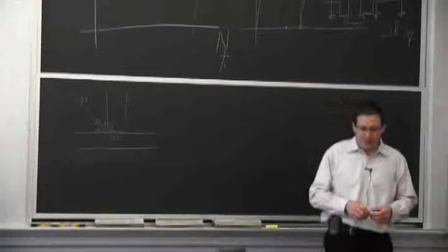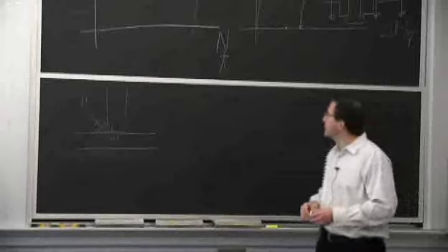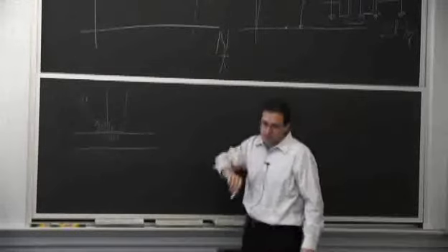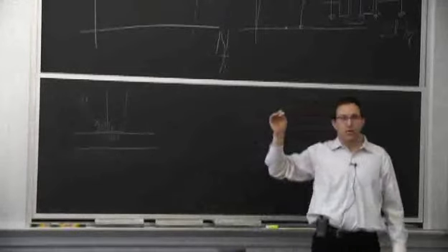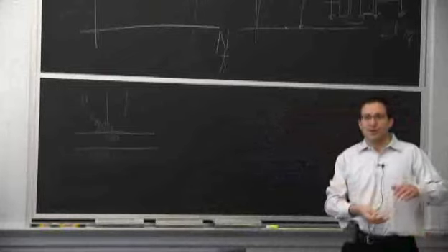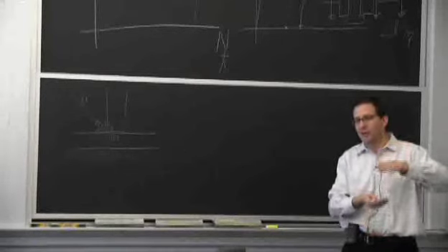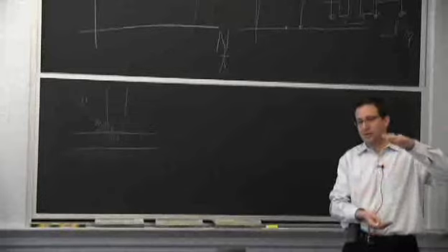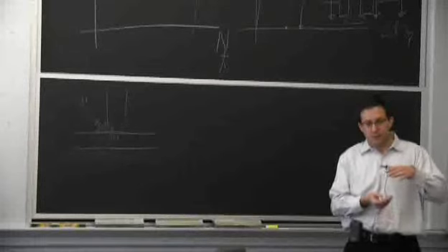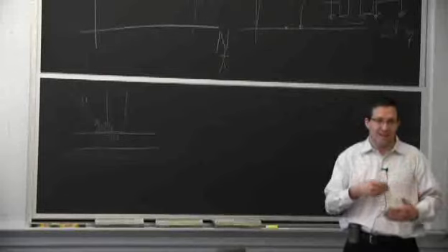Now, the downside, which we haven't talked a whole lot about, is for this type of fatigue here, stress life fatigue. Normally, the higher the yield strength, the more resistant you are, because you can essentially just get the springs to deform back and forth. The closer you get to the yield strength, in this case maybe even just half the yield strength, you start having other things going on that are not reversible, so you're accumulating damage.